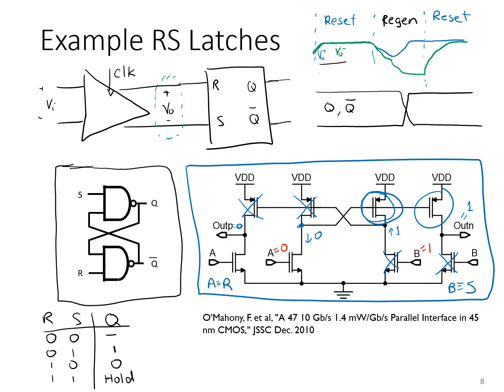Well, now this transistor turns on, but initially at least, even though this transistor is now off, this node here is kind of floating temporarily, and it'll still be at its low logic level, which means that the pull-up transistor here will still be on. So you'll temporarily have a situation where these two transistors are fighting each other to determine whether this node here is high or low.